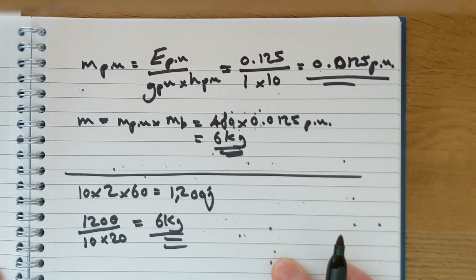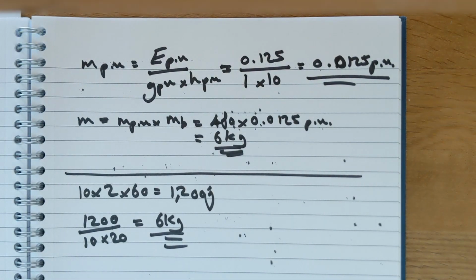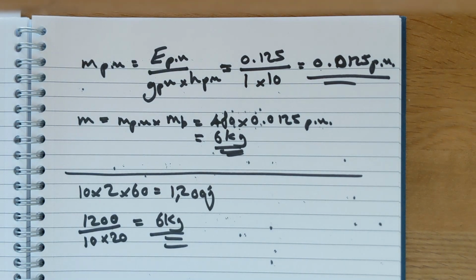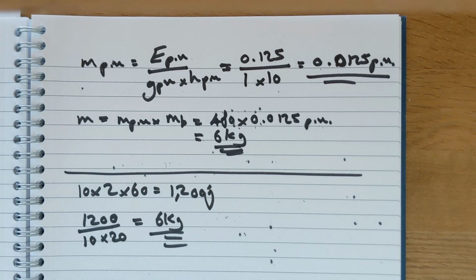The main reason why per unit makes power systems engineering problems more simple is that it helps get around having to keep changing voltage and current due to the existence of transformers on the network, because pretty much all power systems have transformers on them, and switching voltage and current laboriously as you work out the flows across whole networks with multiple transformers can be avoided as long as you convert everything to per unit, and we'll discuss that in the next video.